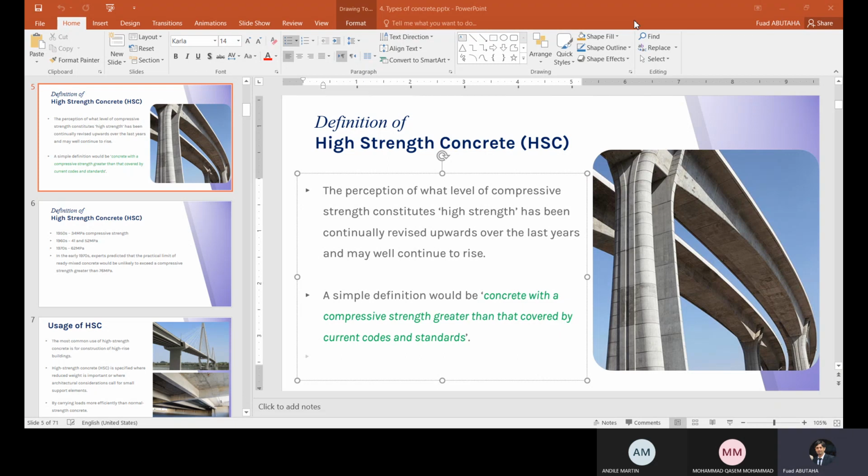You can also save money by reducing the use of super plasticizer. And in the site, I'm sure that not all of them know the effect of the particle size on the workability and on the strength of concrete.